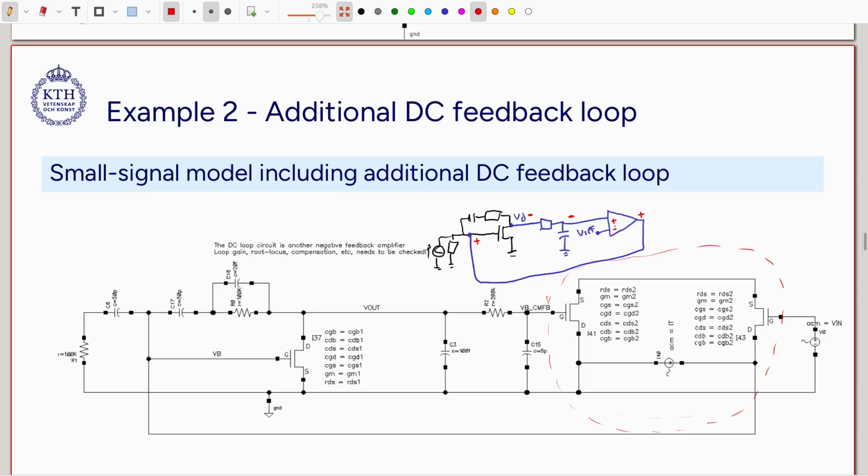So typically the implementation of this amplifier is just a single stage with not so much gain, because now we are worried about stability. So we are mostly considering the noise and basically stability. A single differential pair here as our correction amplifier, and the low pass filter is here.